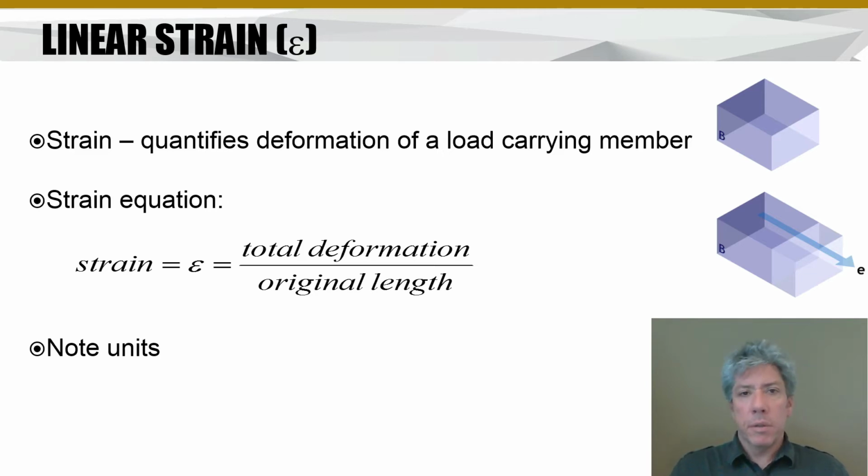Well, all materials stretch as a result of load. Now, how do we quantify the amount that they stretch? Well, we need to measure how far they stretch. One way you could do it is with just length, but that's not particularly convenient. What's better is to figure out how much they stretch by comparison to their original length. So strain is defined as the total deformation over the original length.